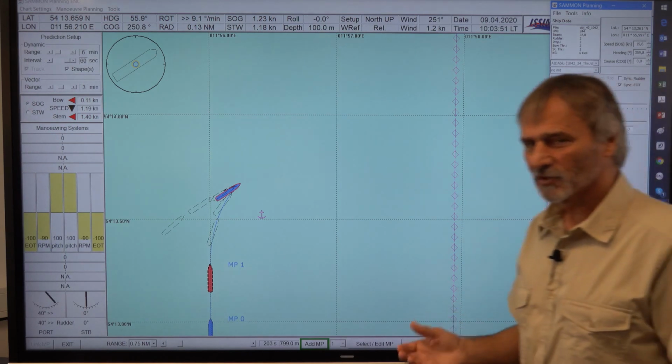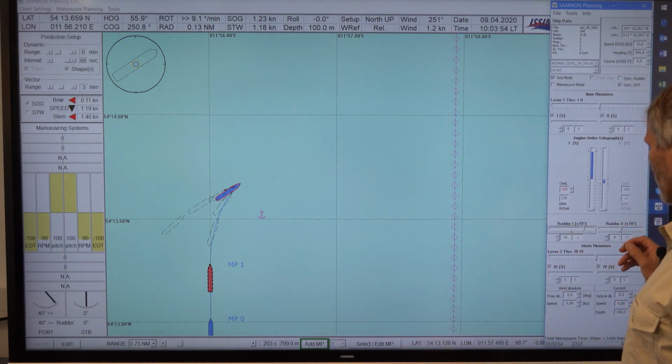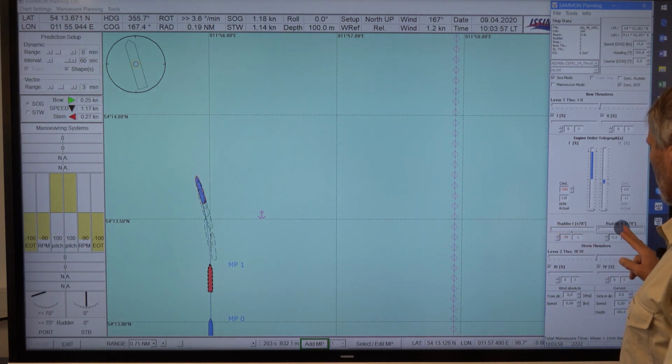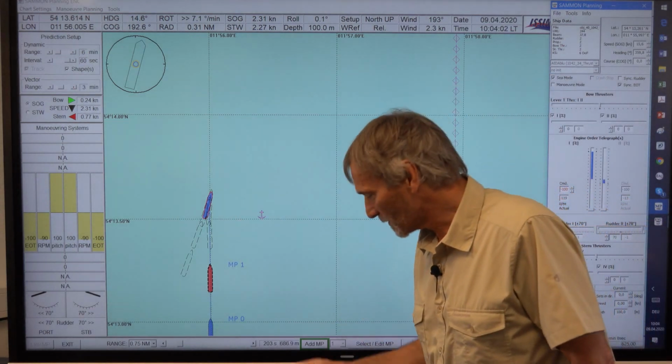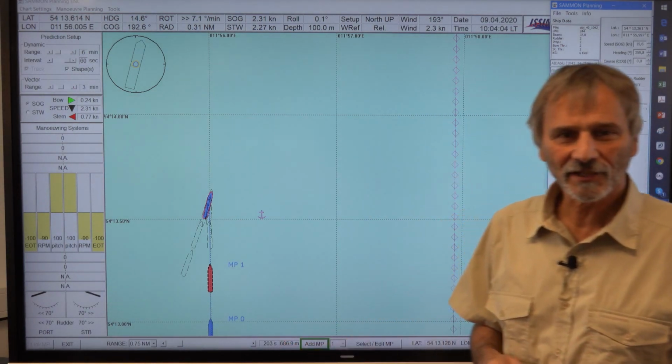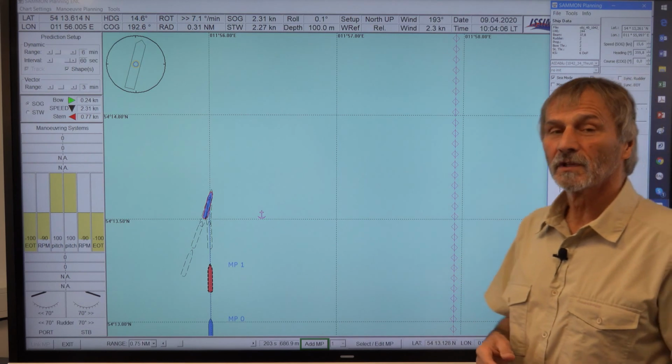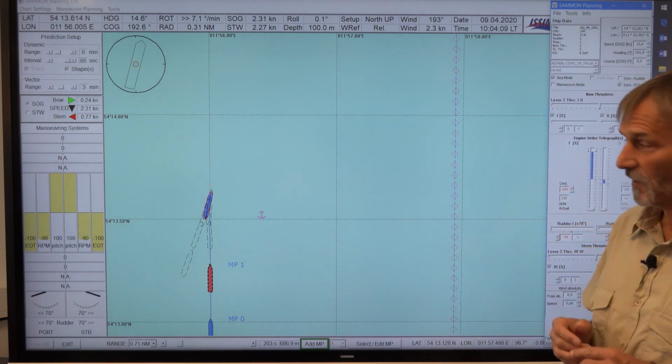So we have many options we could do. In this case, sorry, I used the rudder to the wrong side and to the other side. So this is our smallest stopping distance of less than 700 meters from 15 to 16 knots.